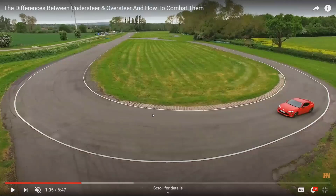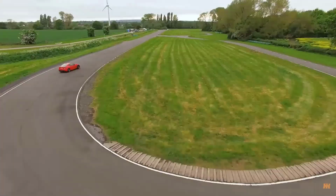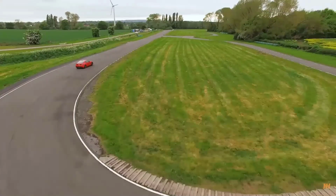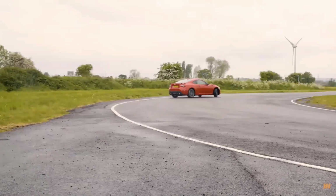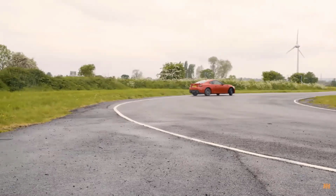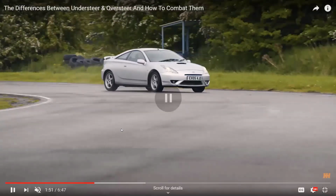If we release the throttle too much, it will tend to oversteer, because all the weight transfer will happen to the front of the vehicle, so the rear end, the rear axle of the vehicle, will be lifted. Because of that, there will be no traction on the rear end, so the vehicle will keep on spinning. It will tend to oversteer in that kind of situation.